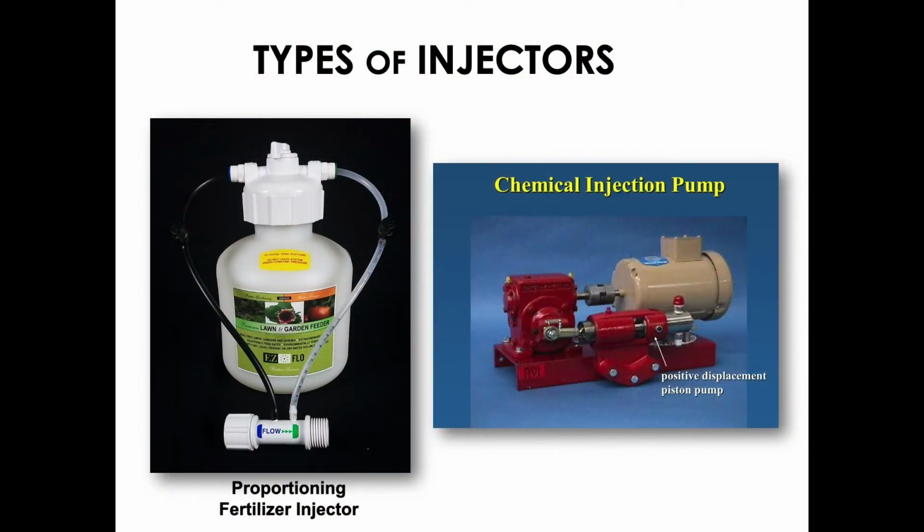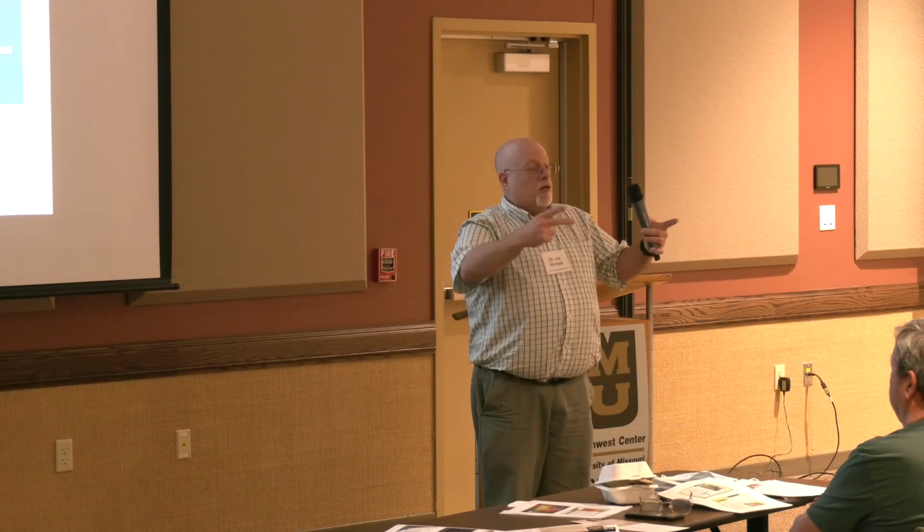So, all right. This is an old style one, a chemical injection pump. These were adapted in the 70s to work with fertigation. You don't see these much anymore. Basically, all these do is that you hook these up into the main line. They will extract this much water from the flow of irrigation. Then they will insert that much, whatever volume it took out, into the flow.